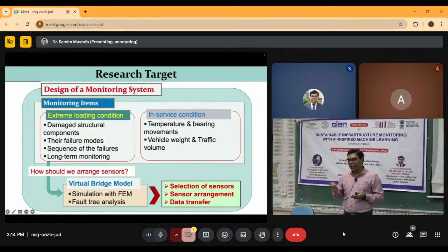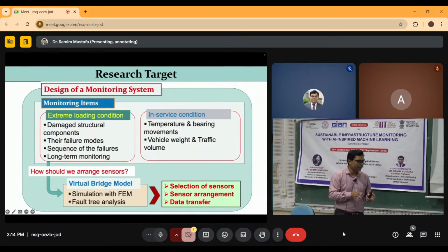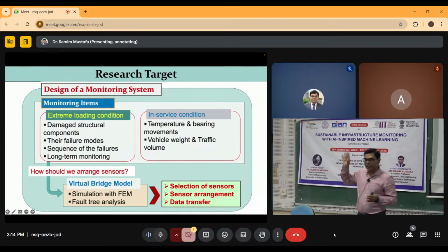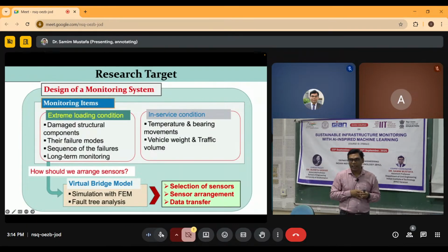So you have that record, and you can input that record into the complex actuator system that the shake table has. Then you can simulate that ground motion on the shake table, fix the prototype structure on it, and it will vibrate in a similar way. But that is only possible for a model or lab-type prototype structure. In an actual real structure we cannot simulate an earthquake. So what should I do for an actual structure?